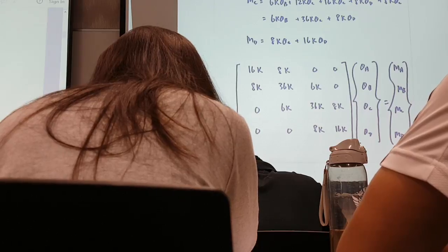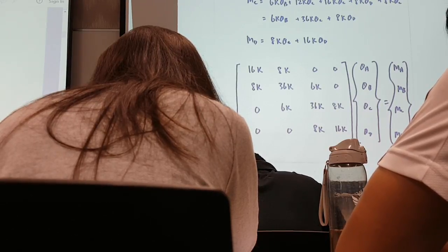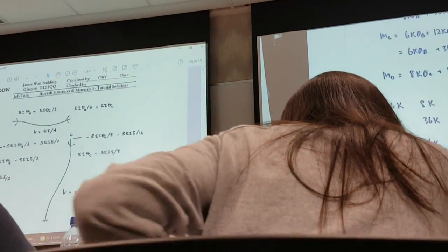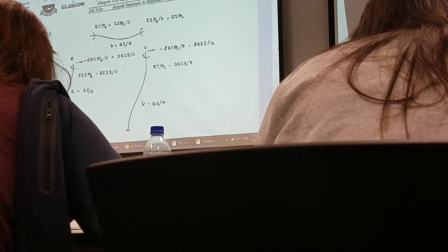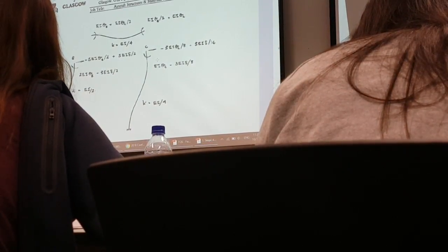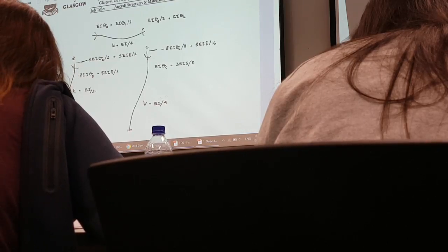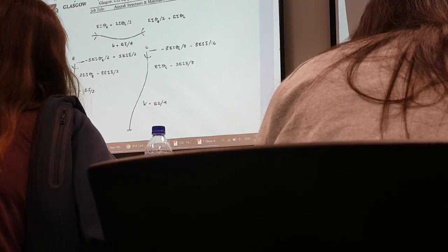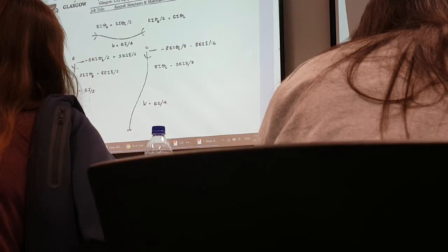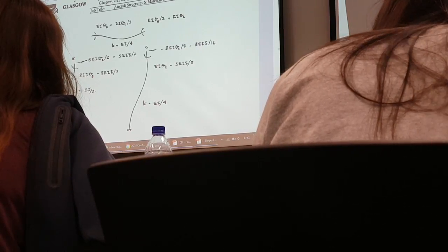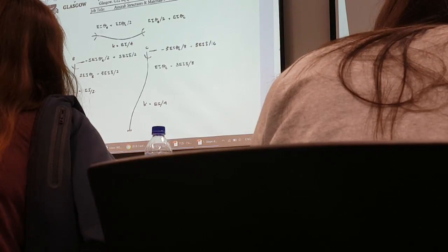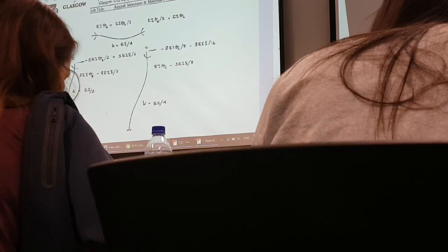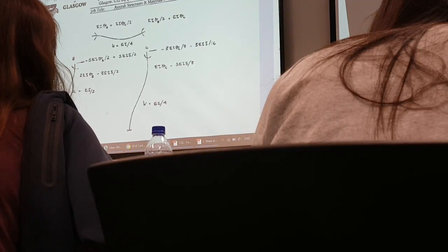Again, in terms of the solution, you must break it down into different individual members. Because as I said, when we went through the slope deflection method, the M1, M2, PY1 and PY2 are member equations, so they apply to each individual member. That's why you have to break the entire frame into individual members. For this case, you can name this as member AB, and this is member BC, and this is member CD. So for this case it is something similar to your, let me see.